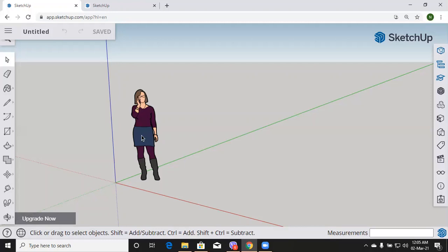To draw any element, you can use the tools on this left side, some grouped into a single button and some ungrouped. Once a tool is enabled, you can define object points and size either by clicking on the preview or by typing precise values.